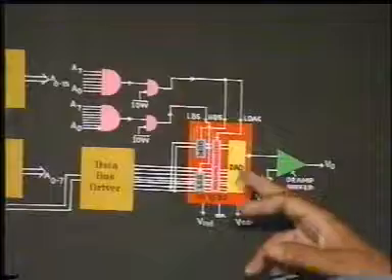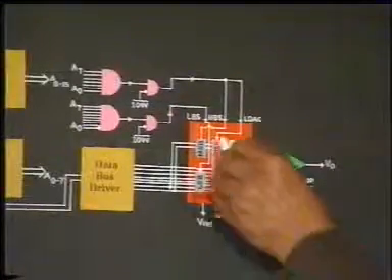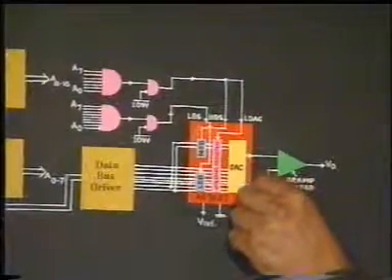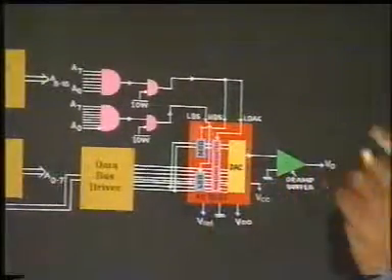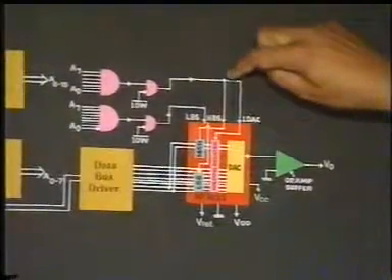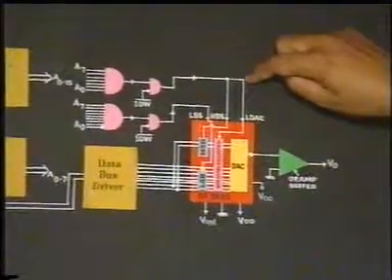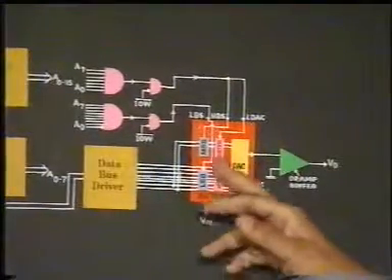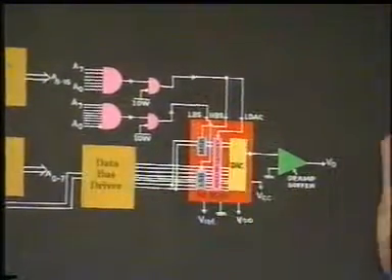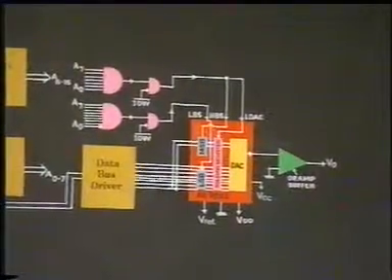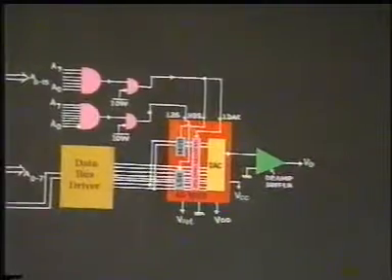After the 2 bytes of data have been latched, both are simultaneously presented to the DAC by enabling the holding register through a control signal LDAC. Here incidentally it is connected with the HBS. So as soon as the second byte is latched, the data is presented. And after conversion, of course, the data is used by the analog devices.